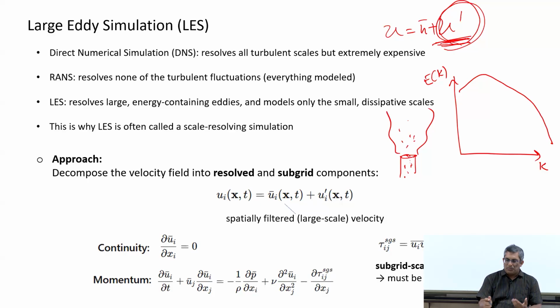For modeling purposes, we can do this, but a flow is a flow. That itself does not have mean or fluctuating components in reality, right? What you have is instantaneous velocity, and particles interact with that. So all these factors are important when we consider multiphase flows.